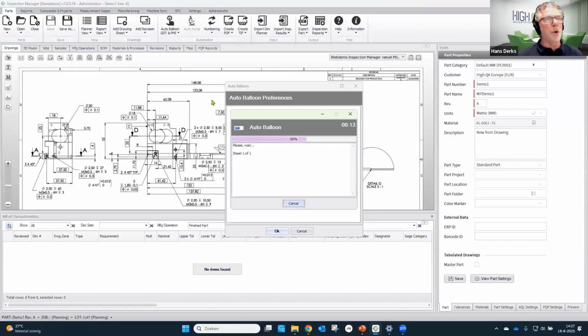And with that font, our OCR engine, optical character recognition, will recognize individual characters, symbols, numbers, letters, whatever is on the drawing. And in the last phase, it'll combine all those numbers and characters into dimensions based on what is allowed by the standard. So it has knowledge on how a dimension on a technical drawing can look like. And I'll show you in a second what that means.